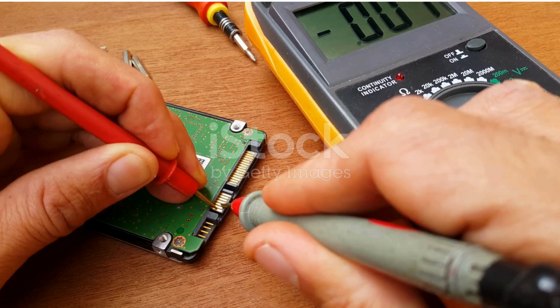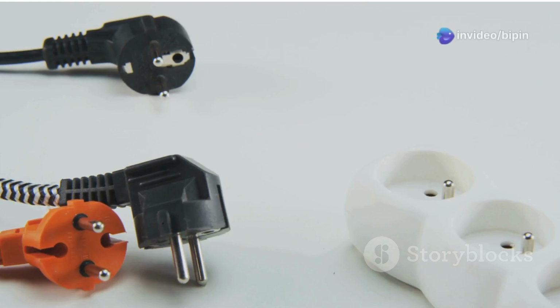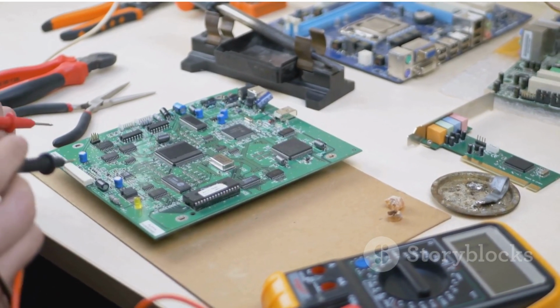Section 9. Testing time. Does it work? With your circuit assembled, it's time for the moment of truth: testing. Connect your circuit to a power source if required, and verify that it functions as intended. Use a multimeter to check for continuity and voltage at different points in the circuit.